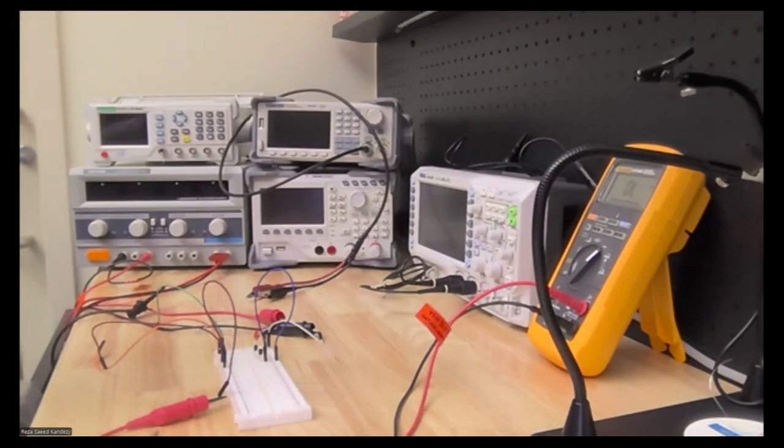So there is a capacitor between the gate and the semiconductor, and the other two terminals, the drain and source. So each time that you turn on the circuit, there is gonna be a certain level of capacitance build up in your MOSFET. Okay, so if you do not discharge that capacitor, it would affect the performance of your circuit. I'm gonna show you actually what's gonna happen.